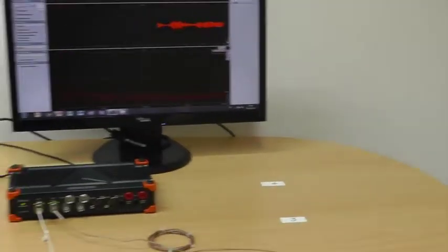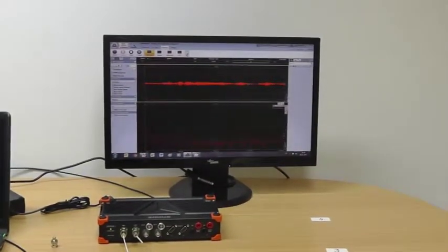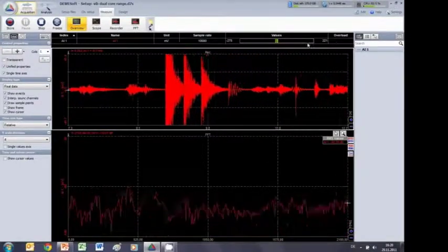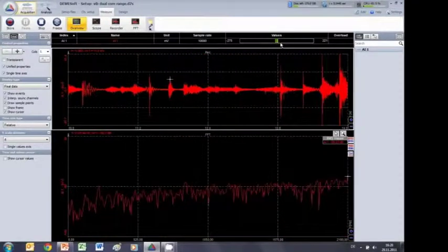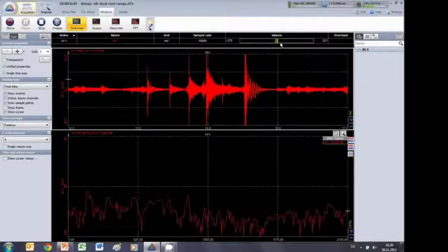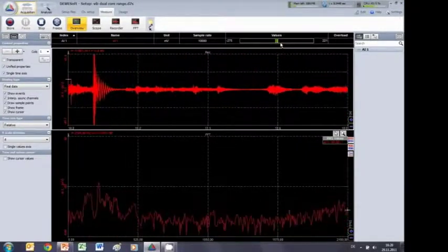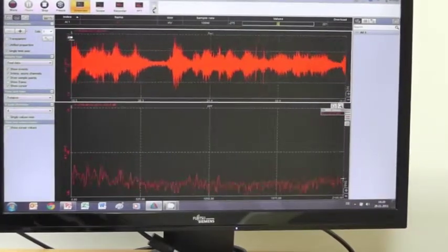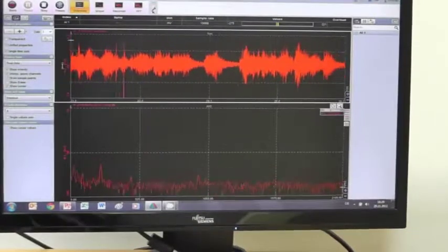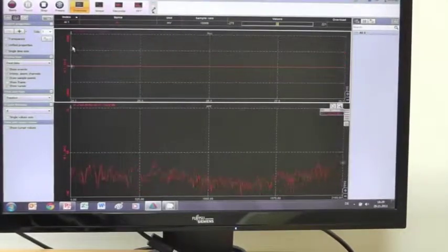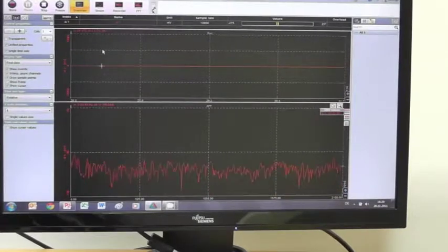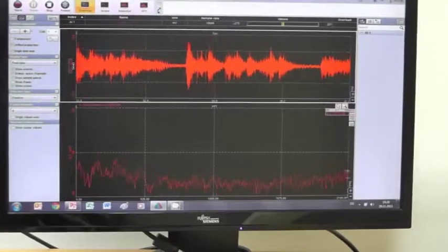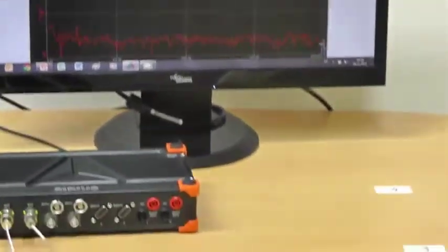So here we see the recorder signal, and you can see already my voice is recorded. Here on top we can see the dynamic range, and when you look at the small detail, how much we really record, on the scaling you could see maybe this is 10 millivolts plus minus. If I go to full range, you see this is 10,000 millivolt full range. So how about now? We don't see anything, but if I just make auto scale, you can see the small tiny signal coming from this sensor.